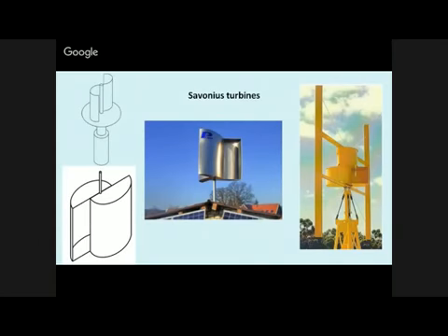After Darrieus, the other important vertical axis turbine is the Savonius turbine, in which a scoop is used, where two scoops are there. Across this side the friction is less, and therefore it rotates in the clockwise direction. Sometimes a scoop is also given at the bottom. Different shapes are there. For self-starting purposes, three scoops are provided, as in the center diagram. Whenever the wind velocity is there, this is based upon drag, and a drag-based design is less efficient.